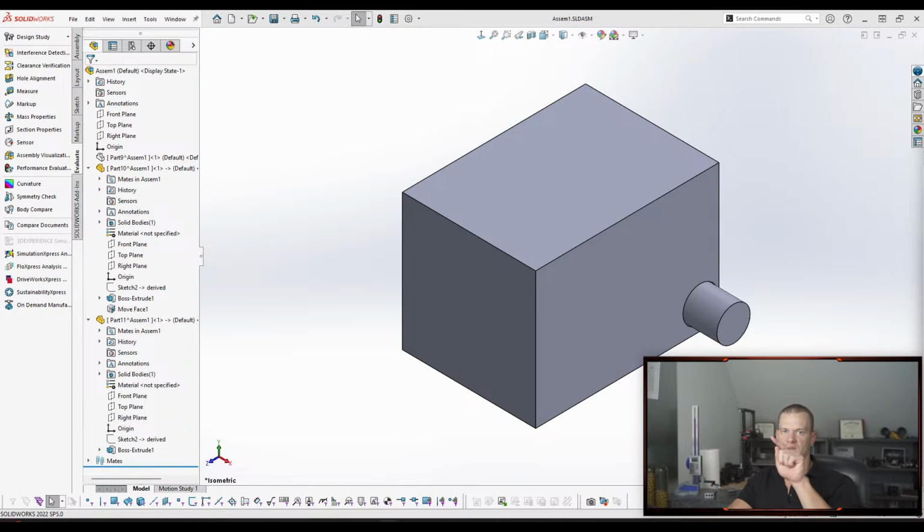I can go in and change my 1 degree draft to 3 degrees and my nominal thickness from a quarter to an eighth. And when I hit go, every one of my parts will update and just trickle through, and then there's no going back and wondering, did I miss something? It's awesome when you set it up the right way, and it saves you a ton of work.